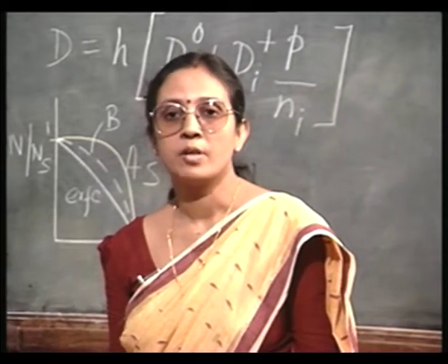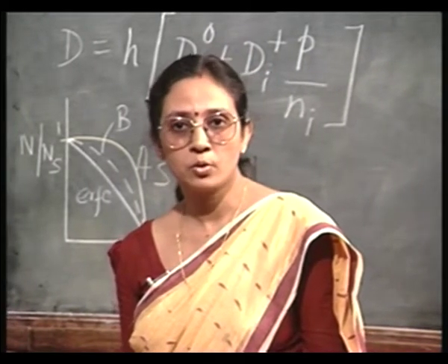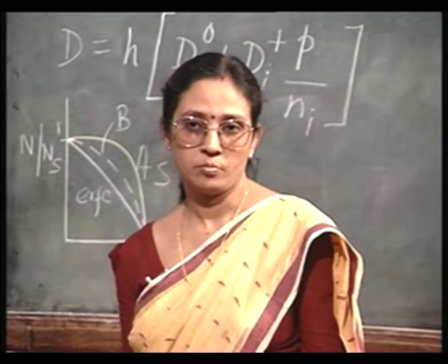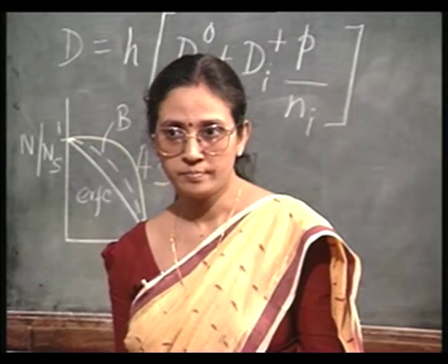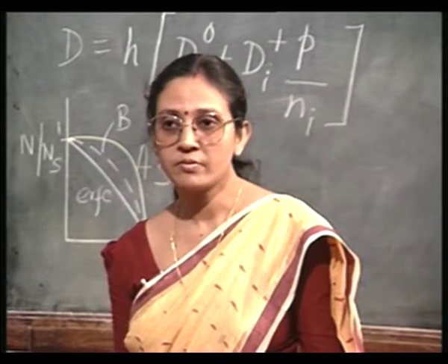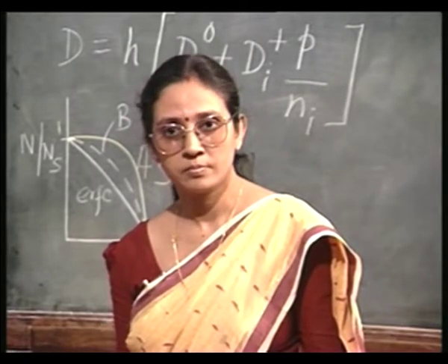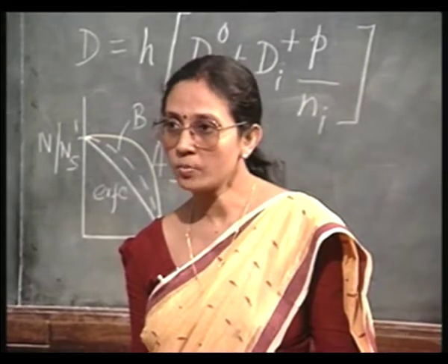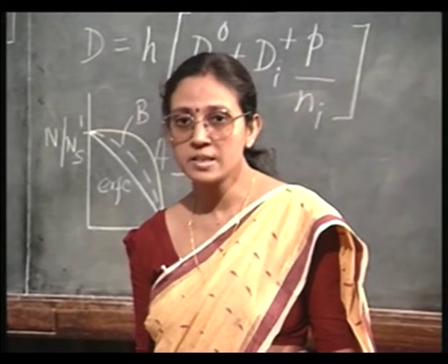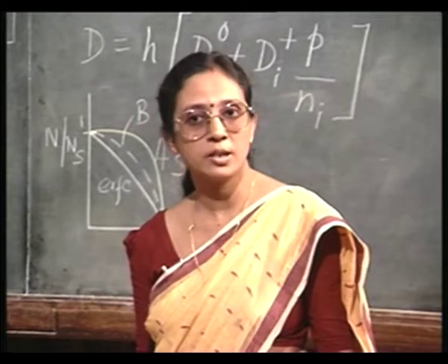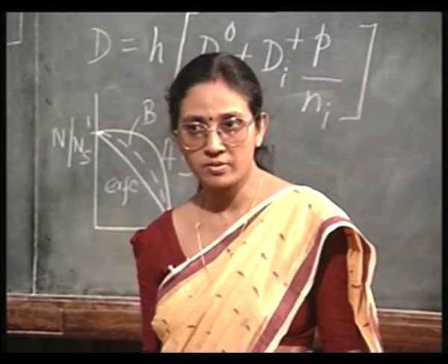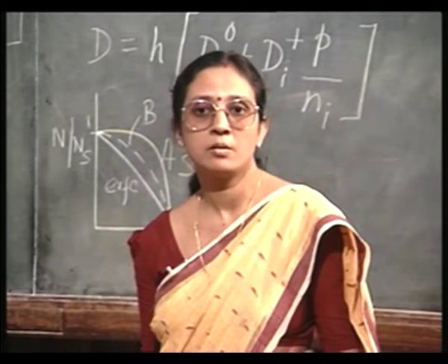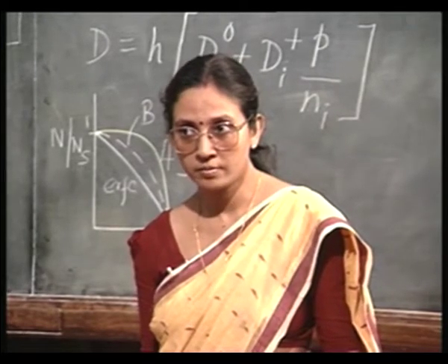As the Fermi level sweeps below 0.11 electron volt below the conduction band, some of the levels must be empty. So, it is not possible for these vacancies to retain all the electrons, right. The levels above the Fermi level must be unoccupied.